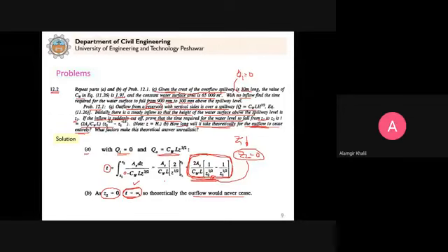So what could be the possible factors that give this unrealistic solution? Factors which make this theoretical answer unrealistic include surface tension, surface ripples, evaporation, leakage, and seepage losses. We already know that from a reservoir there can be evaporation from the water surface. Similarly, there can be water seepage down into the soil. These factors we did not consider while deriving the equation for the time, so they can be responsible for why we get the time as infinity.